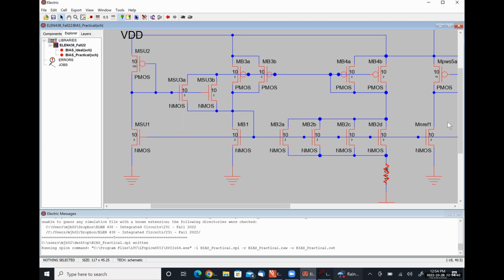You just change the name of the transistor. Yeah, because the PMOS and NMOS stuff has a spice model, but then you use miscellaneous annotation text. Is that going to copy over? No, because it's not attached to the transistor, it's just annotation next to it. So you need to copy that as well.